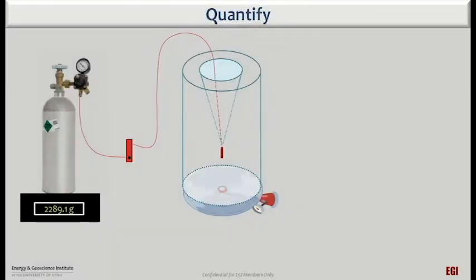Building smaller scale versions of the vent on the Union roof allowed us to control as many variables as possible. The key in this decision was the realization that we could directly measure the mass flux entering a bench scale model by weighing a canister of CO2 and recording its change in mass over time. The vents were designed as follows.